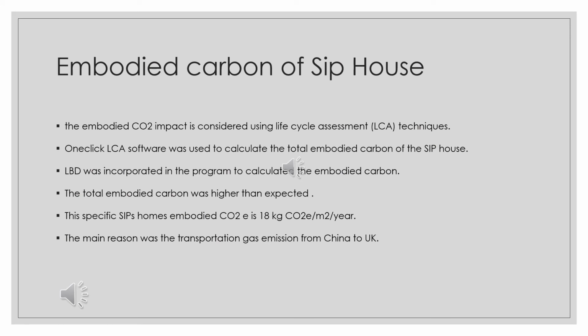To calculate the total carbon emission from the SIP home, I've used One Click LCA. It covers all life cycle stages from cradle to grave, with separate reporting for the extraction of raw material, manufacturing, transportation, on-site construction, operation, and disposal and reuse at the end of life. However, I have eliminated the operational part because I only wanted to focus on the embodied carbon.